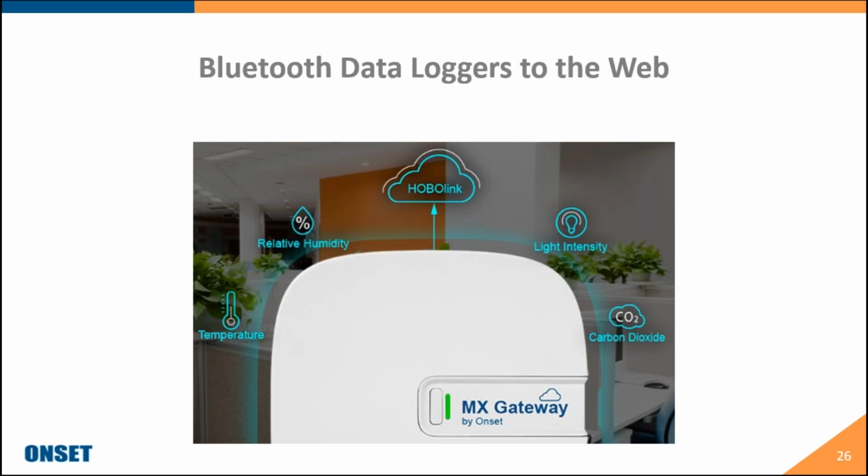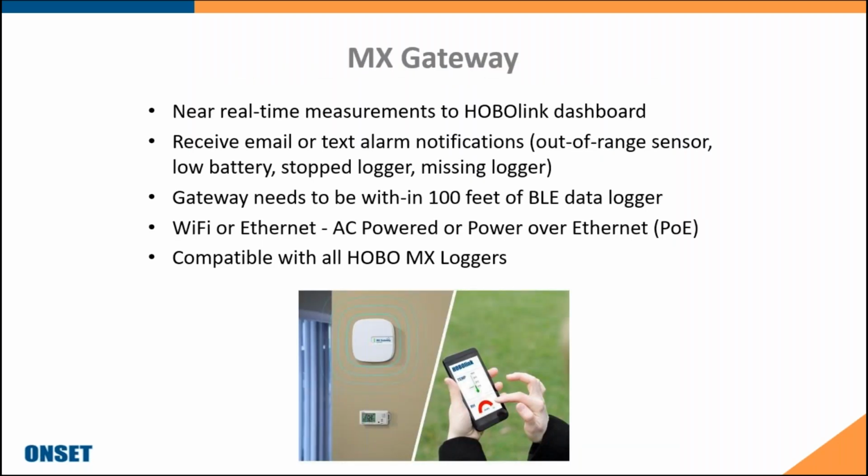Now, as I mentioned earlier in the webinar, our Bluetooth data loggers can be part of a remote monitoring solution, and that would be with the incorporation of our MX Gateway. The MX Gateway will give you real-time data to your HOBOlink dashboard. Again, any data loggers within 100 feet line of sight range will be able to connect to a single gateway, and up to 100 data loggers can connect to a single gateway.